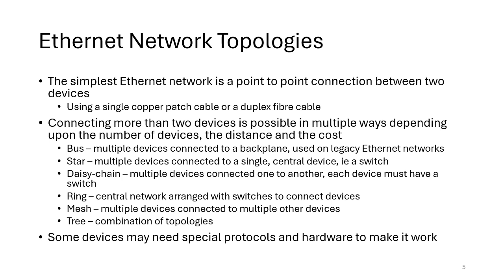Now, more complex networks would be arranged as a ring. If you use standard Ethernet and connect it in a ring, you will crash the network because all of the messages will be routed around the ring continuously, and very quickly, within a few milliseconds, the ring messages would have been repeated so often the network would be overloaded.